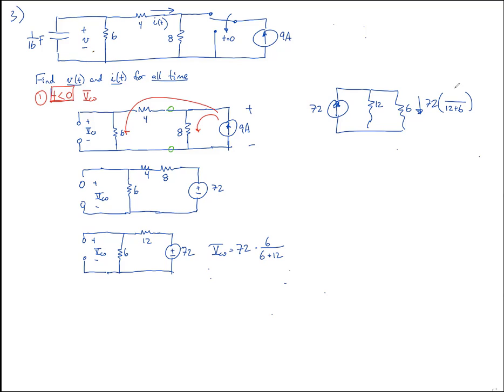So it's got to be ohms on top to cancel the ohms on the bottom, when multiplied by the current gives you current. So what's in the top? We just said it's not 12 times 6, because that would give you ohms squared up here, divided by ohms gives you ohms times amps, which makes the entire thing volts. And it doesn't make sense to say the current through this is some amount of voltage.